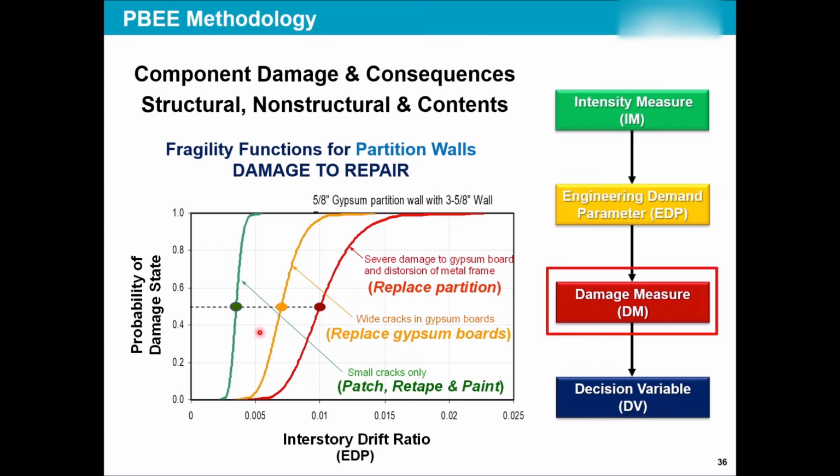Now that we got those responses from our structures, we can simply convert them to the stuff that you already know, fragility functions and vulnerability functions. Later on, again, a session will be dedicated to how to translate those engineering demand parameters, get the help of intensity measures of the earthquake, combine these and come up with such curves, which are probability versus an engineering demand parameter, which clearly indicates the performance of the building under different engineering demand parameters or different intensity measures.